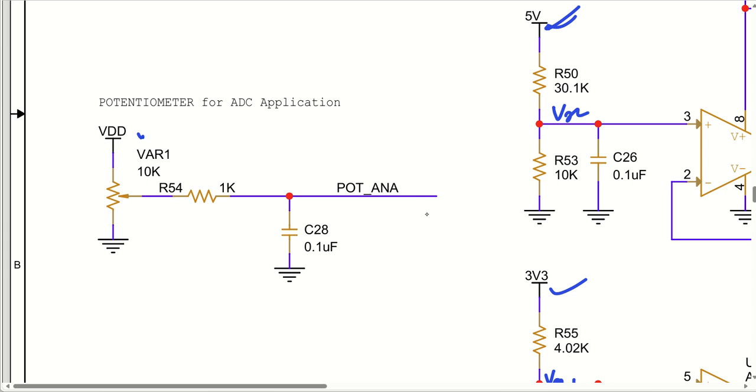Coming back to the other part, we had talked about the potentiometer as well. So we have one potentiometer connected to 3.3 volt, with the resistance variation, let's say Rx and Ry. Based on that there will be a voltage difference here, and this voltage goes to my ADC pin. So this is how a very nice application of the potentiometer can be verified.